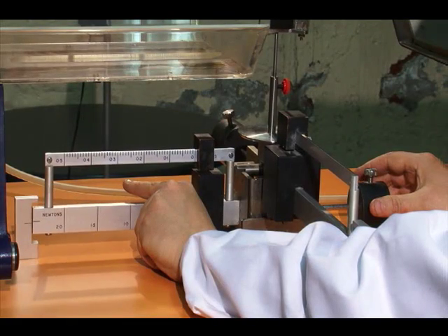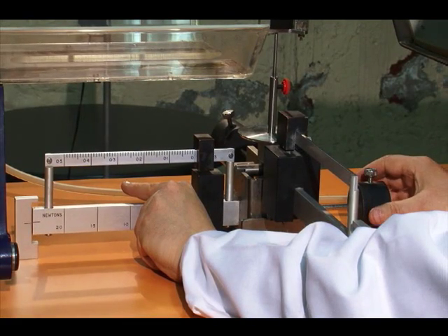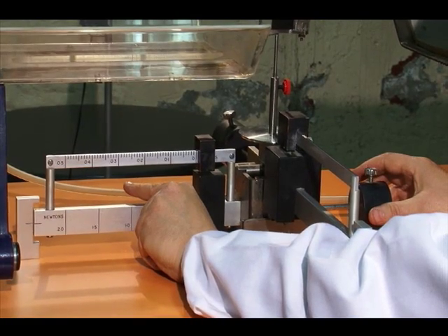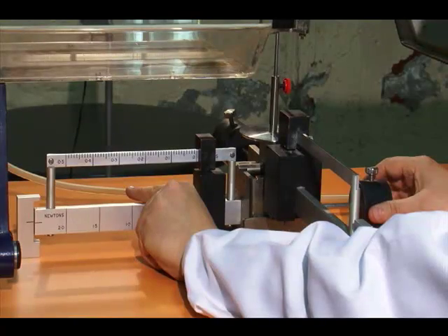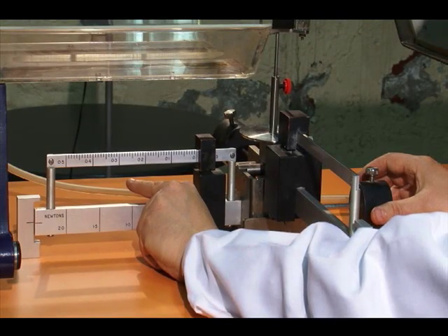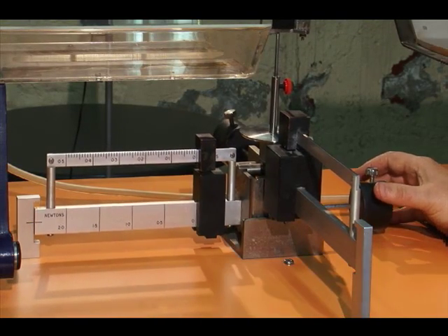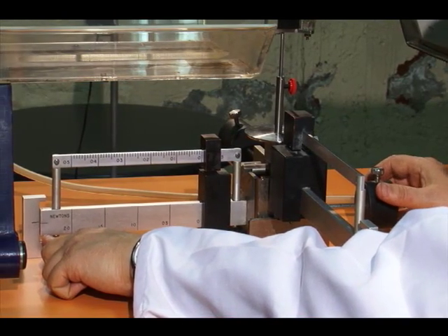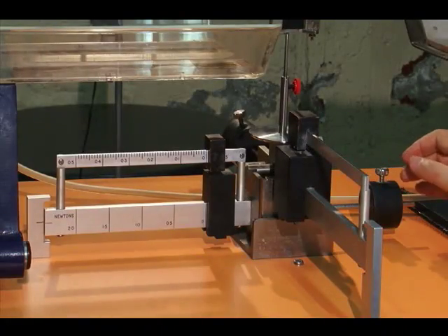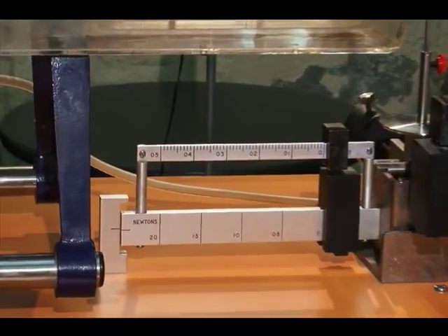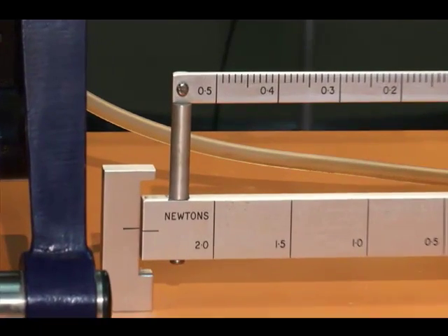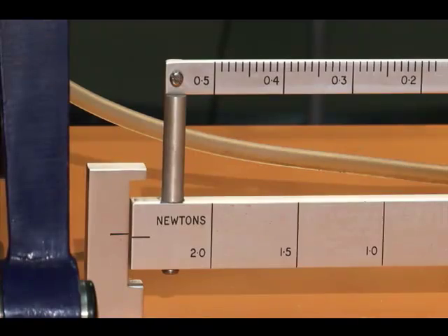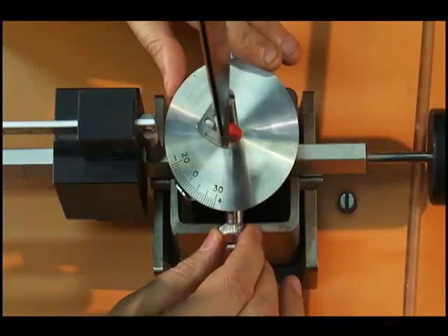The 2-component balance consists of a pair of balances supported on knife edges on mutually perpendicular axes parallel to and normal to the axial center of the tunnel. Lift and drag components of force exerted on the models under testing are balanced by sliding 2 weights along the arms of the balance until a state of null deflection is reached. Graduations in Newton units of force allow lift and drag to be read directly.